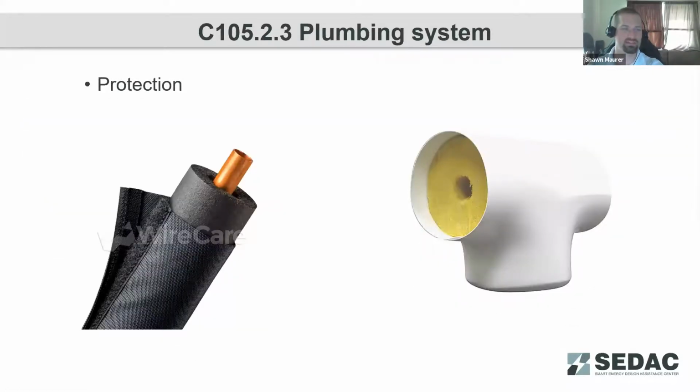As far as protecting the insulation on these plumbing systems, the insulation does need to have protection from physical damage, UV damage, weather effects. There's two types of jackets we're showing here. The white all-purpose PVC jackets, a little more common for, again, chilled water lines, larger hot water lines, insulation that's exterior to the building. For smaller refrigeration systems, copper lined systems that have those kind of peel and stick around insulation wraps.